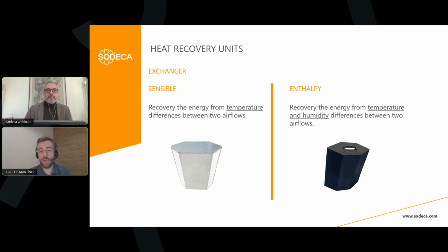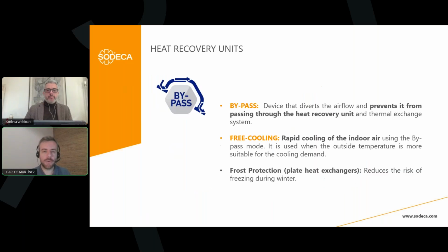Okay, so speaking clearly, enthalpy we will use in coast cities or places with high humidity levels, and sensible we will use in the rest of the projects. Okay, so another important characteristic of the heat recovery unit, not all the heat recovery units in the market have it or have it automatically, is the bypass.